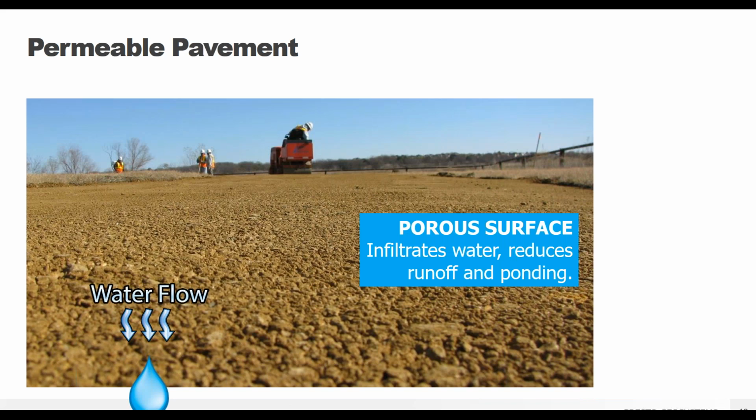And so one important advantage to any unpaved yard utilizing GeoWeb stabilization is going to be that use of an open graded aggregate course. Since you don't need fines to achieve compaction when you're using the GeoWeb system, this system can actually act like an on-site detention basin, storing water within the void space of the GeoWeb infill.